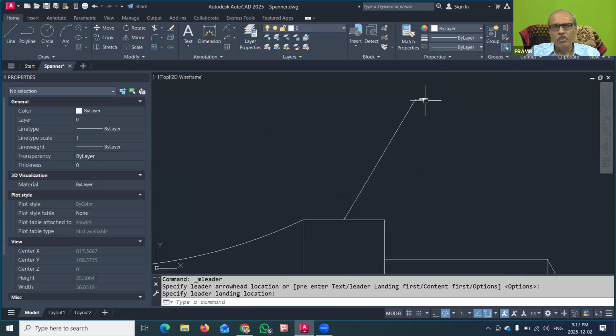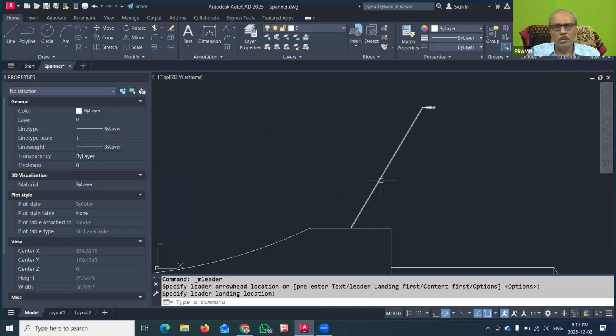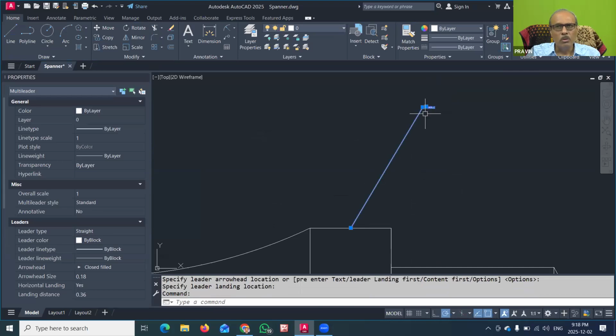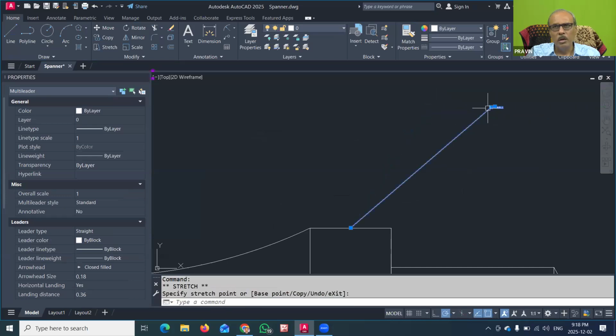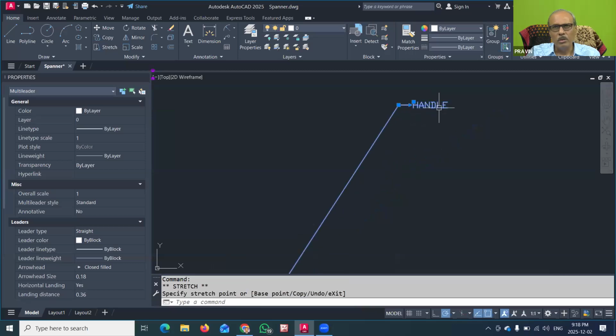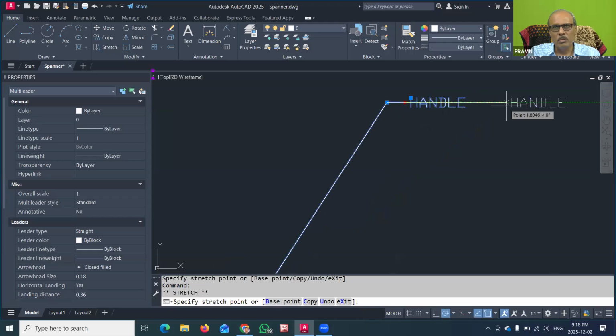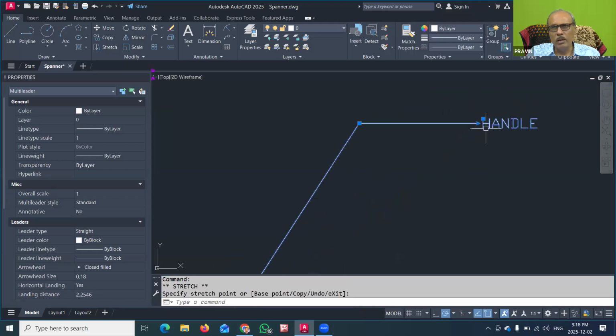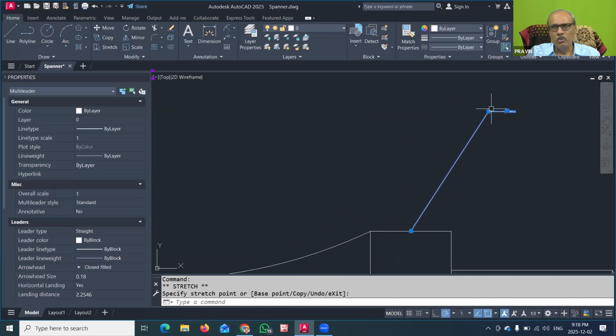So you can see that in this way, this object was shown with the dimension. But here, although the sizes were not proper, you can increase the text height. You can edit this in the grip option. You can lengthen this line also a little bit. You can then grip adjust this horizontal line, and then you can just stretch this distance. Yes, this arrow you can use to adjust that. And then here, suppose it is a little longer, you can just choose it again here.